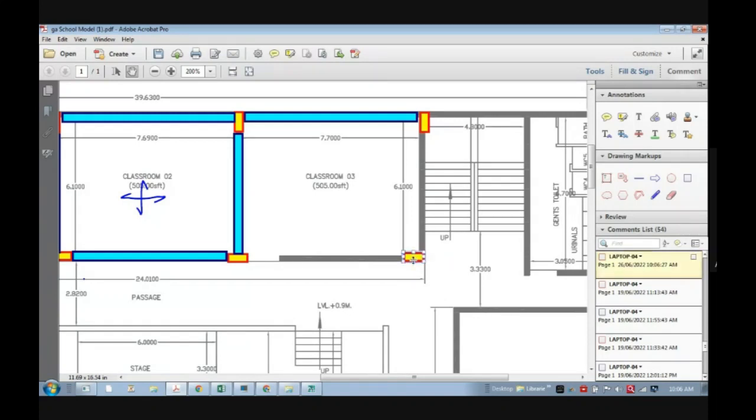Now, when I shift this like this, you will see that your beam will not rest clearly here because this column is also to the right side. And generally it is not accepted inside the staircase. So I will shift this also. Okay. And then I can rest this beam over here. Now it is okay. And then the same beam I will rest over here.